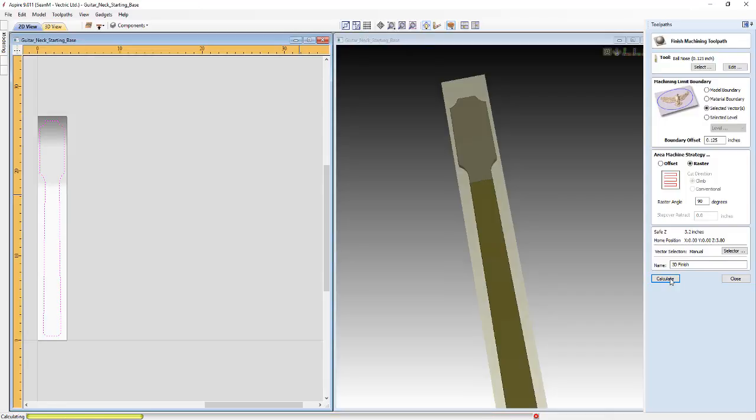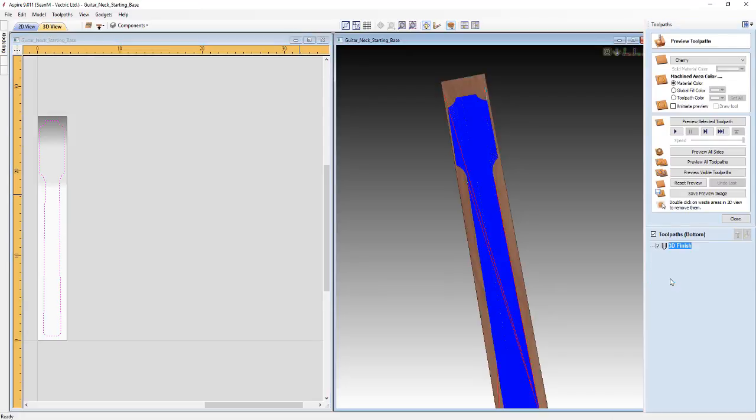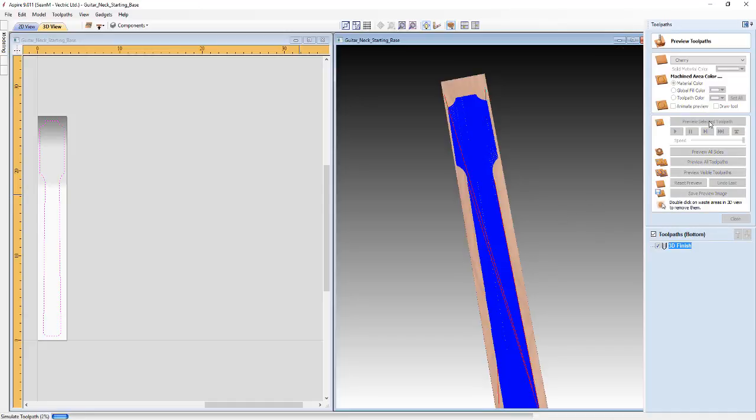And the reason for that is because the actual dead center of a tool, especially a ball nose tool, is the only part that actually ever cuts down to the specified depth, so the full flat level of that particular side's model. And we're going to end up with basically a lot of cusping and very thin film around the edge. So if I just preview this, I can show you exactly what I mean.